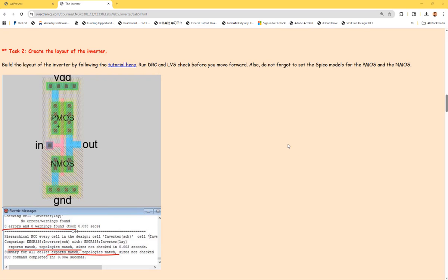What are these? What's the name of that component? This is NMOS, right? So what is this? P-tap, right? Because NMOS needs a P plus. I forgot that. So NMOS needs a P-tap, so it's a well tap. P sub is the P well, even though it's not really a well. The whole wafer is the well, P sub. So this is the P plus.